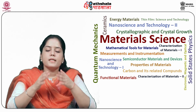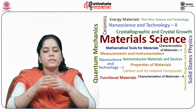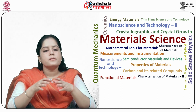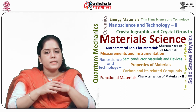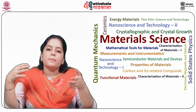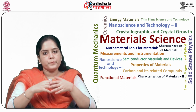Thermal oxidation is carried out at 1100 degrees Celsius plus or minus 10 degrees Celsius in 100% oxygen ambient. The wet oxidation of silicon was performed for 10 hours by passing water vapors with oxygen gas.